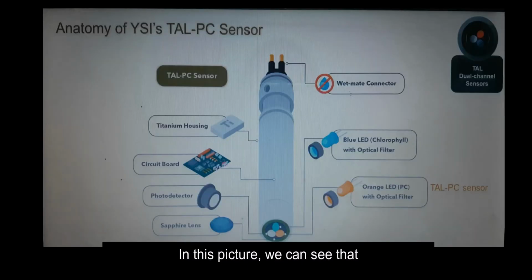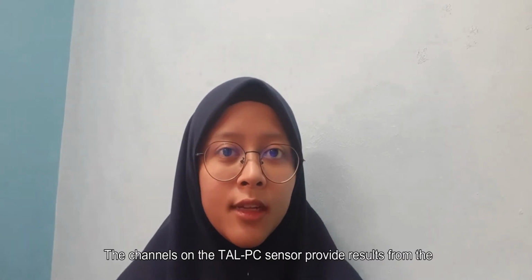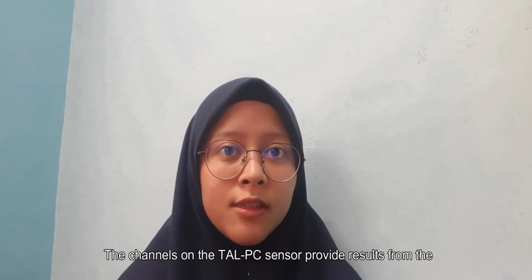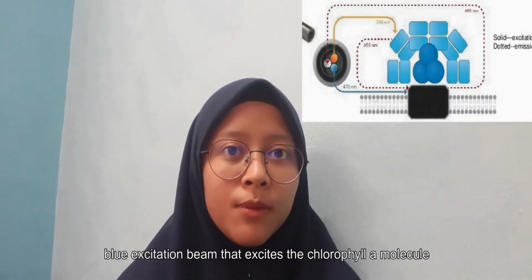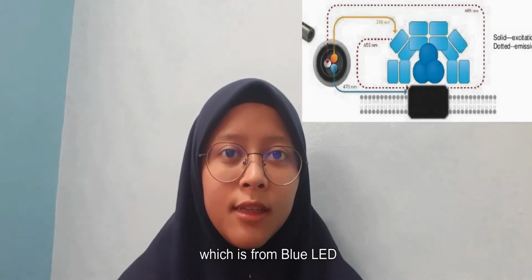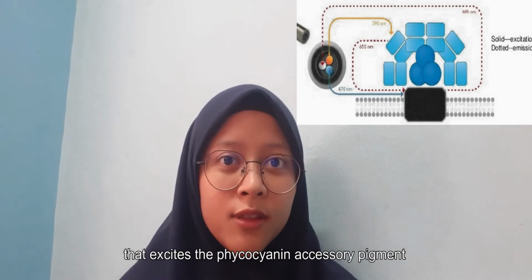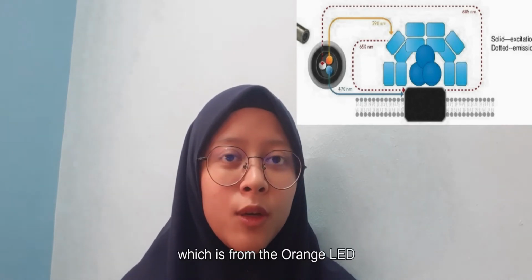In this picture, we can see the compartments of this instrument. There is a circuit board inside the body of the instrument, and the instrument is covered by titanium. There is also a blue LED with optical filter and an orange LED with optical filter, a photodetector and also a sapphire lens. The channels on the total algae phycocyanin sensor provide results from the blue excitation beam, which is from the blue LED, that excites the chlorophyll A molecule, and from the orange excitation beam, which is from the orange LED, that can excite the phycocyanin accessory pigment.